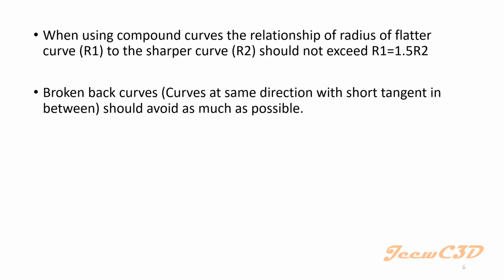Then when using compound curves, that means curves going in the same direction without a tangent, when you are using that kind of curve, the radius ratio should be R1 equals 1.5 R2.